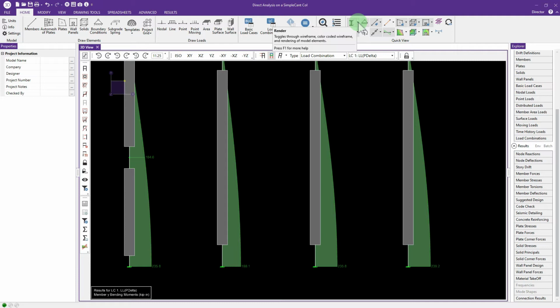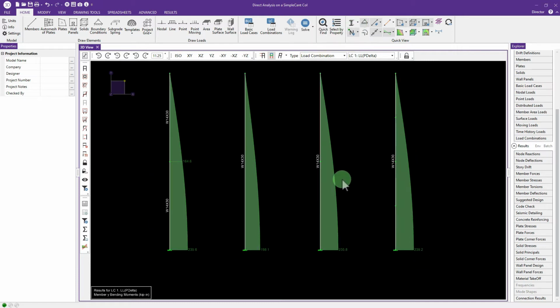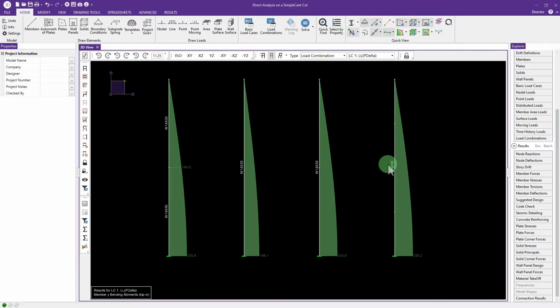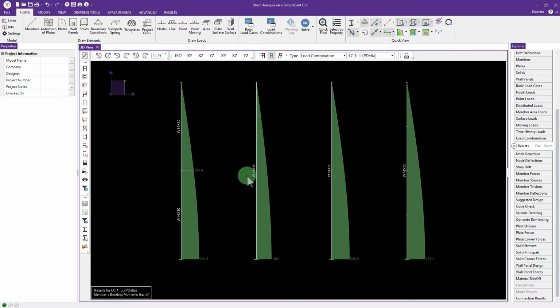Let me go ahead and turn off our 3D view so you can see these nodes. All right. So even if you're using the geometric nonlinear stiffness method, it is still inaccurate to only have two nodes between your element as far as a critical structure.